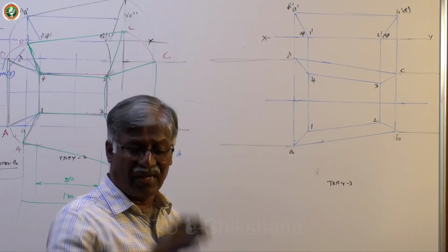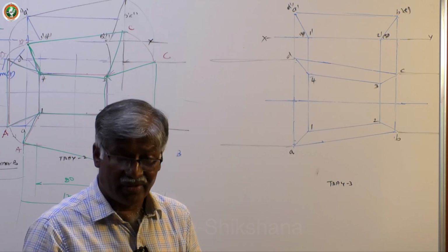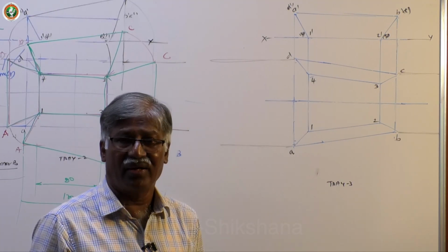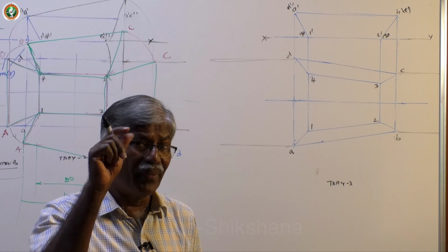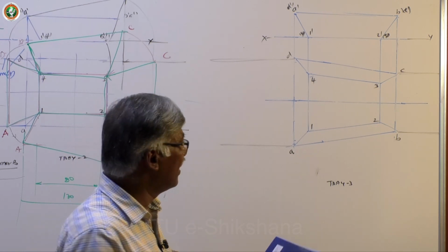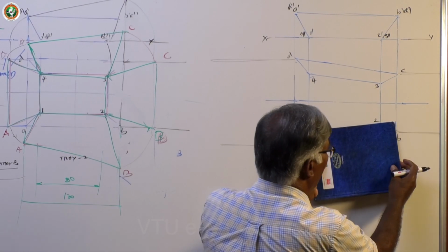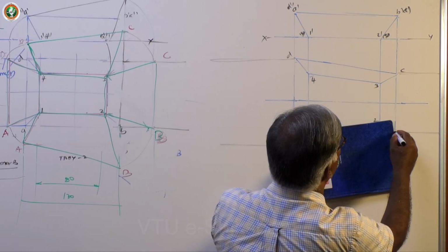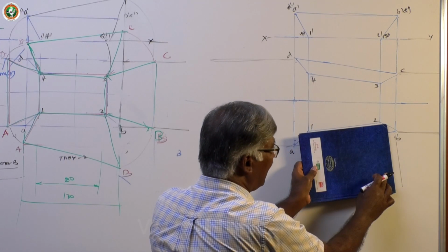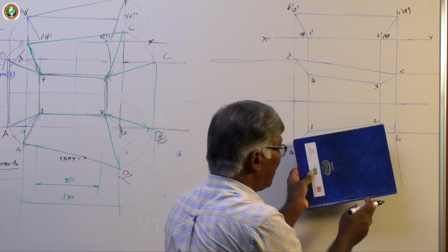It is somewhat inclined. So what you have to do is have the set square or the protractor, anything. In case of computer, you can use perpendicular line reference and do it. Now assume that I have maintained 90° and through B you have to draw a line, you have to maintain perpendicularity with 1, 2. So it is very interesting. See, this is not vertical. You have to maintain 90° with respect to the imaginary lines continued 1, 2 and 2B, or you can keep it this way.